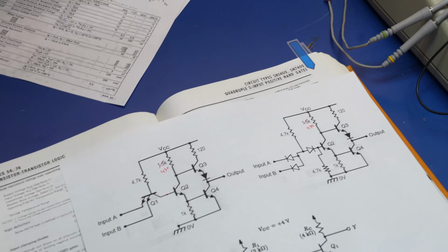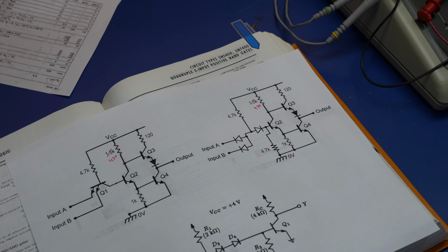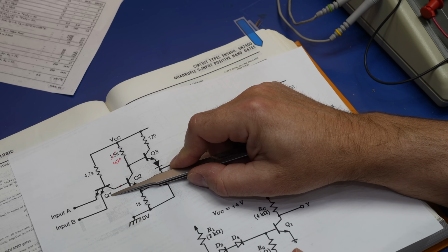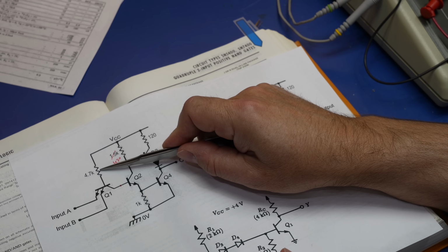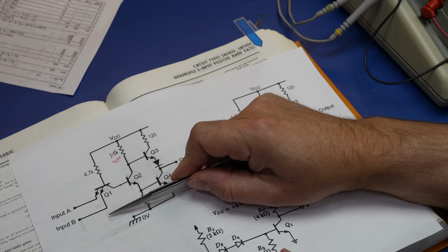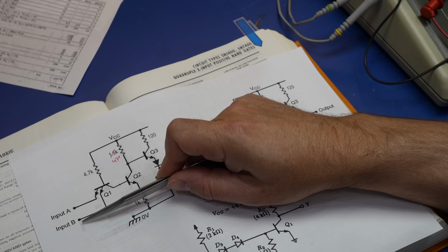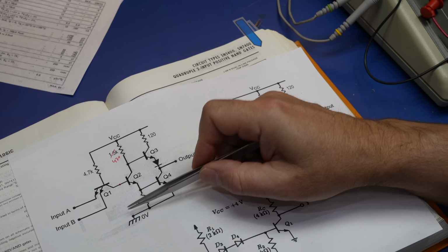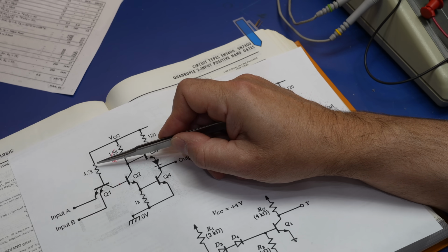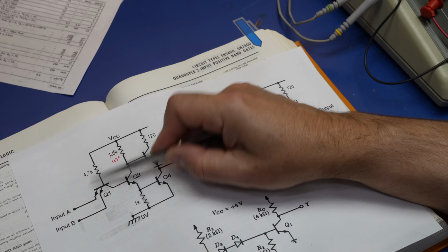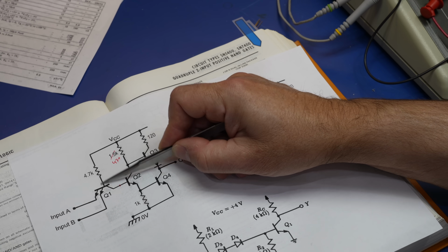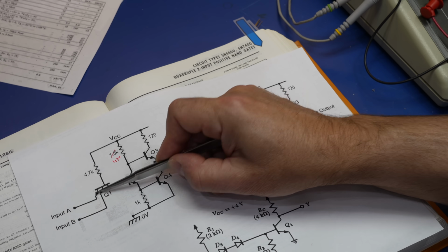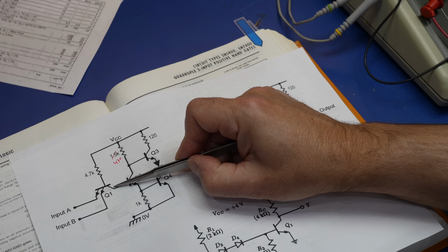You may ask, if you're really astute, a further question. This transistor Q1 also has a saturation. When its inputs are driven low, it is going to reach saturation. So how come it has no problem when the input goes back up here? The reason is that it stays in saturation. When the base current goes to 0, it goes instead to the base to collector diode, and all the carriers are evacuated through this. So it doesn't matter because it can switch while staying under saturation.